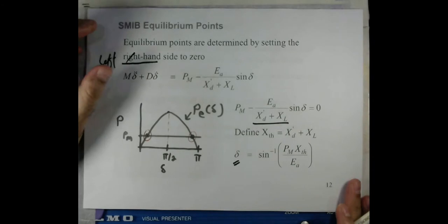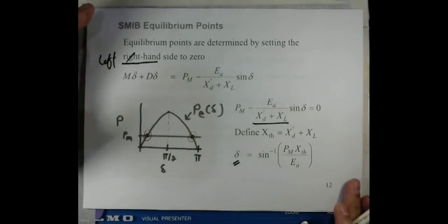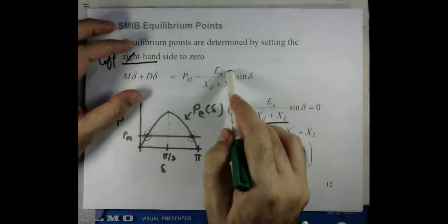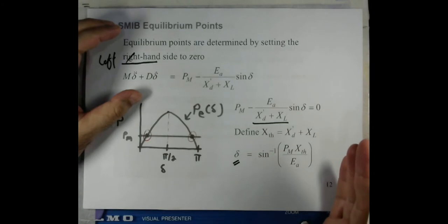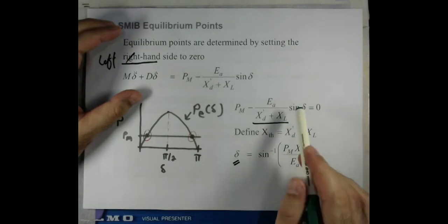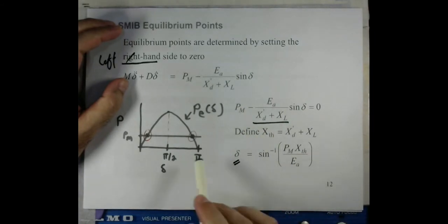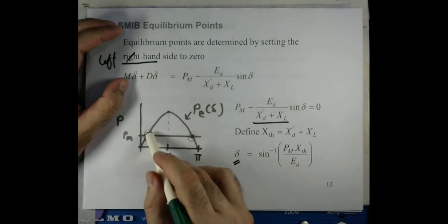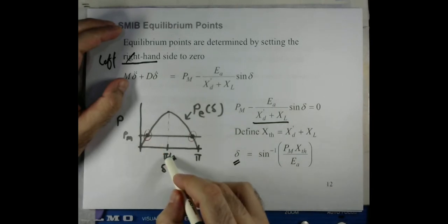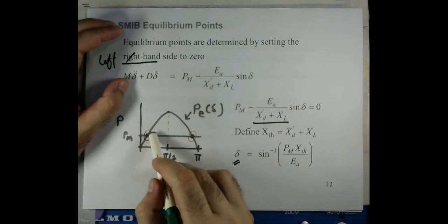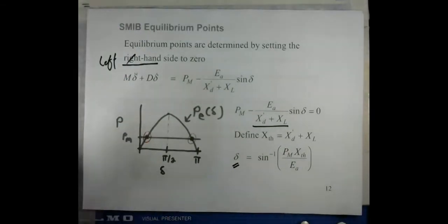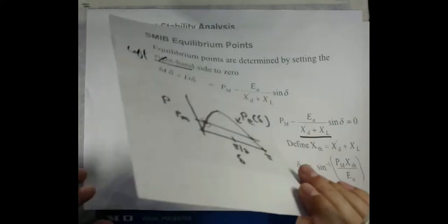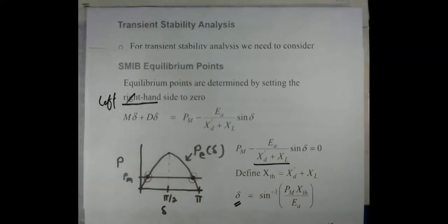And for determining the equilibrium points where the two powers are equal, the right side will be 0. So then we put that to 0, and we found the two possible points of operation, and we discussed that the angle on the left side of the maximum theoretical angle, which is 90 degrees, leads to stable operation, while this point leads to unstable operation. We discussed that in detail, and then afterwards we discussed that, let's say,